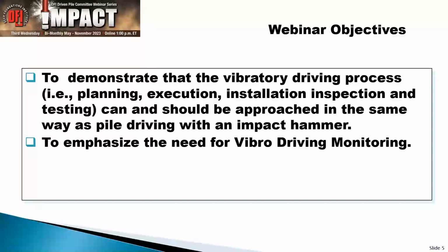But it means, realistically, that we really need to make a concentrated effort within our industry to start doing monitoring during vibratory driving. Because as I will point out a little bit later in the webinar, that is something that is not commonly done. Most of the time when you talk about vibratory driving, you'll get a story, well, we were able to drive it to a certain penetration. Sometimes a little bit more detailed, like, well, it was fairly easy, or well, it took quite a bit of effort, but that's about the extent of vibratory driving monitoring.